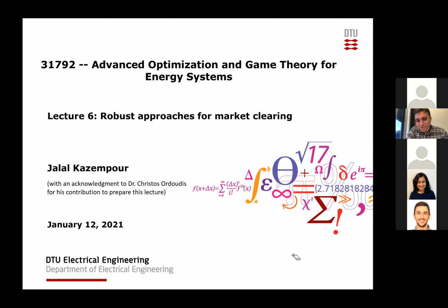Thank you so much. So we still have our day-ahead variables, the schedule of G1, G2, and wind power. Here we again have the production adjustment of generator 2 as our only flexible conventional generator. We have our load shedding under 4 scenarios. We have the wind spill variable under 4 scenarios. I'll talk about beta later.